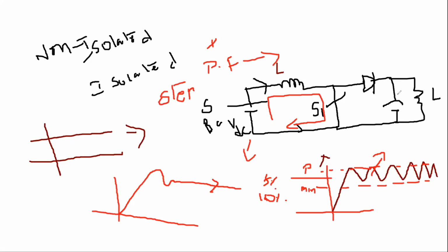And here, why do I keep the capacitor across the load? Why are we placing the capacitor? To minimize the ripples, to minimize the load voltage ripples. At the output, the load voltage. At the input side, we are getting like this. The inductor is charging, then it will send through the diode, then here you will get it. When you are charging the inductor, the capacitor will discharge.